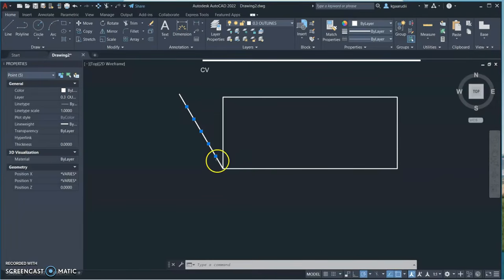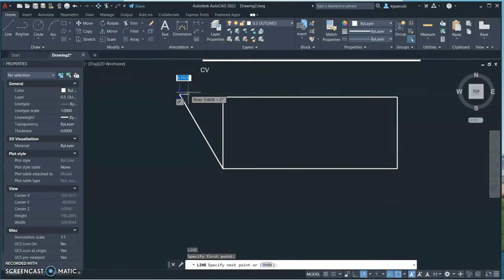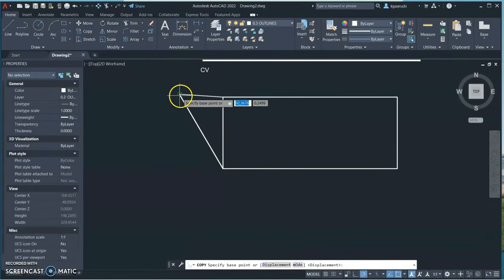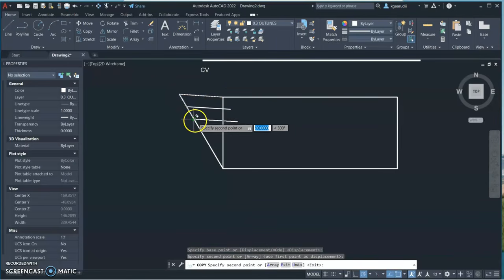8.33 with a ruler. So what we are going to do is let this line help us with the division. So what we need to do now is to join the last point with this point, and then from here, with the help of our set squares, we are going to draw a line at each and every division that we made on this line, and those lines must be parallel to the first line that we drew. So it's going to be something like this.